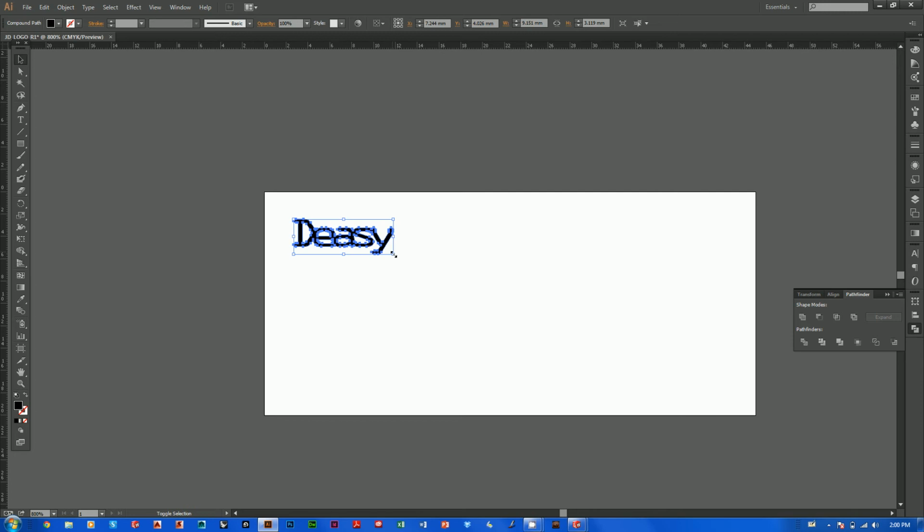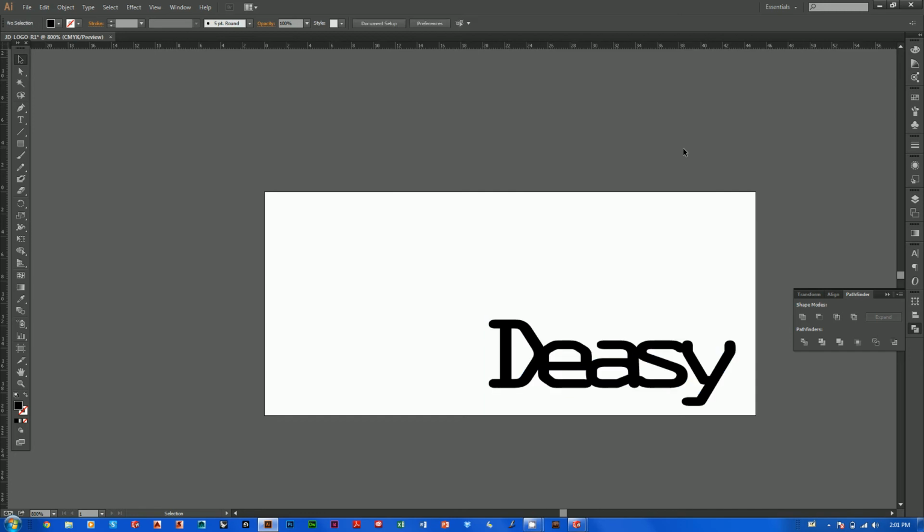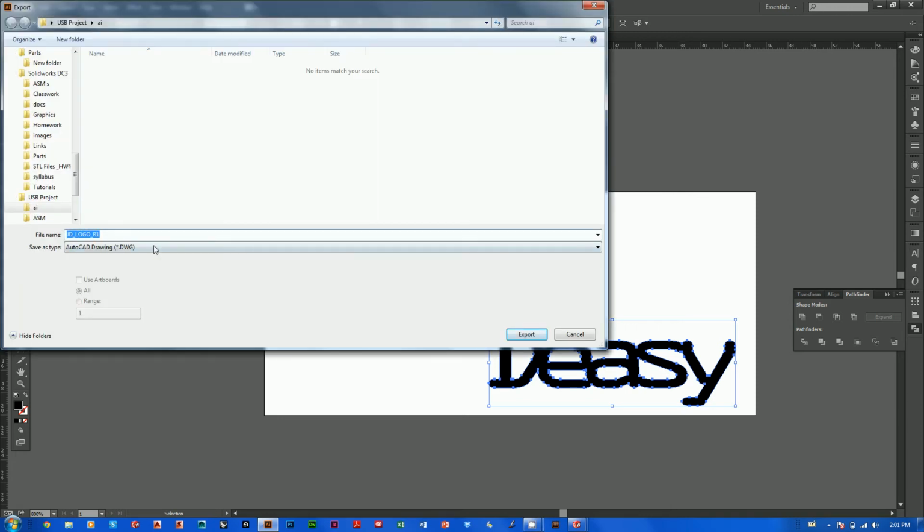I'm going to take this and hold down Shift and drag it out to what I think it should look like on my part. So there we go. Okay. All right. So I'm happy with that. And now the only thing to do is to export. I'll select it first. Here's a fun trick. We can select it first and go to export. All right. And then we're going to save it as a DXF file.